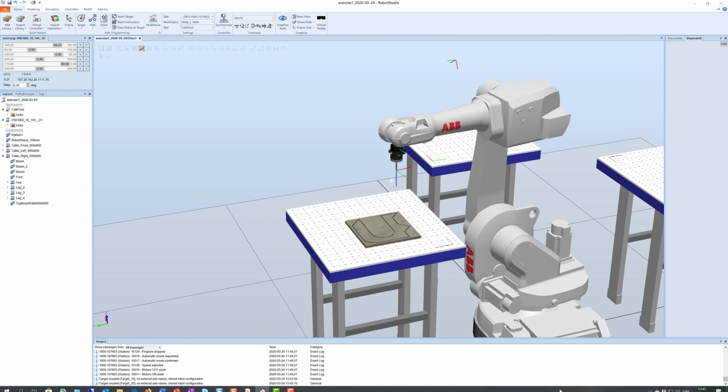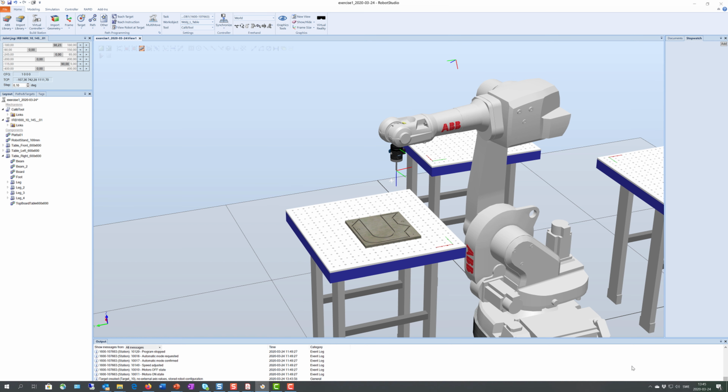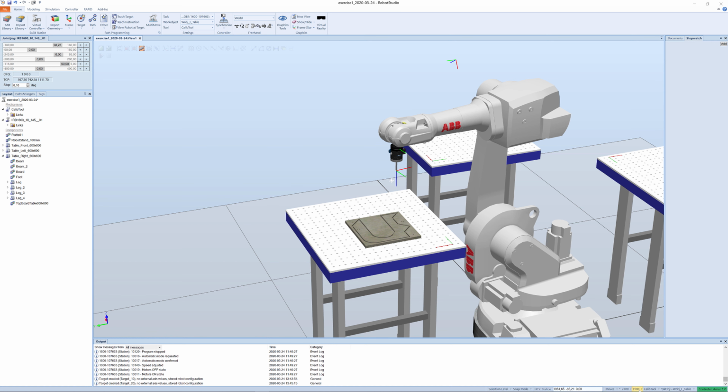Then in the bottom of this, we have a pre-selected arguments for all motions. We can change that later on when we edit the program, so that's not a problem. But we do choose some of the variables or data of the argument that we're going to have for most of the part of the program, like velocity 100 millimeters per second.